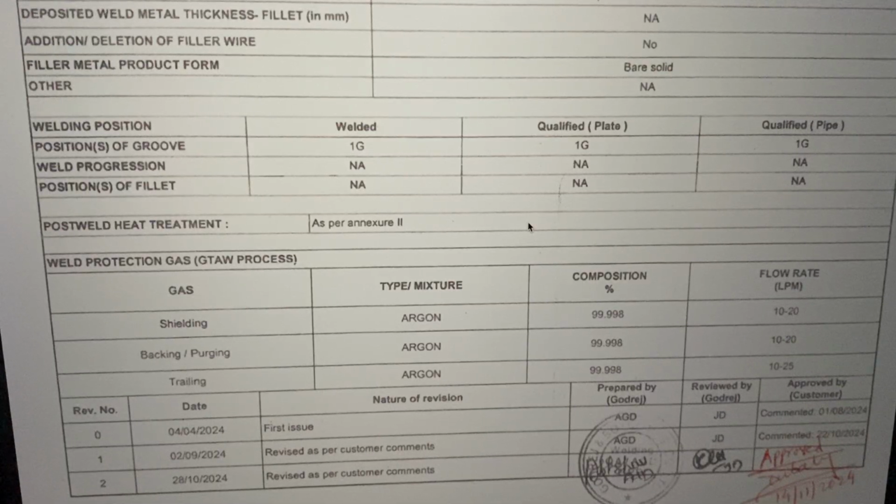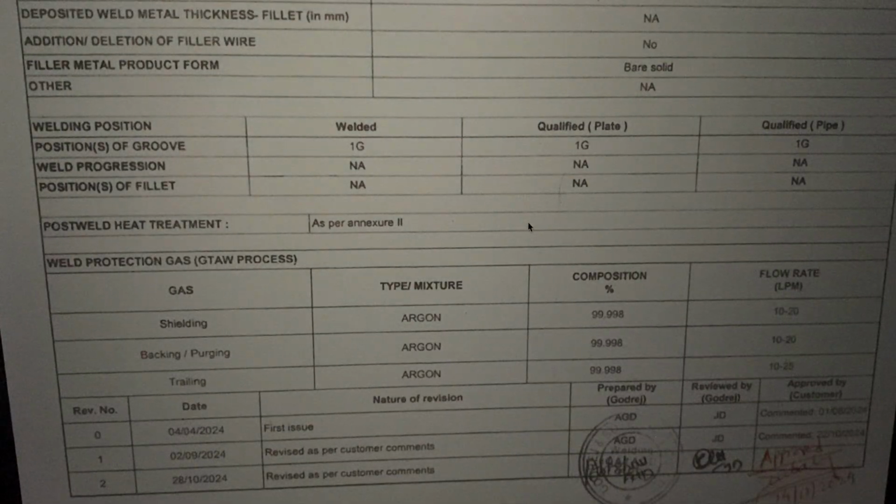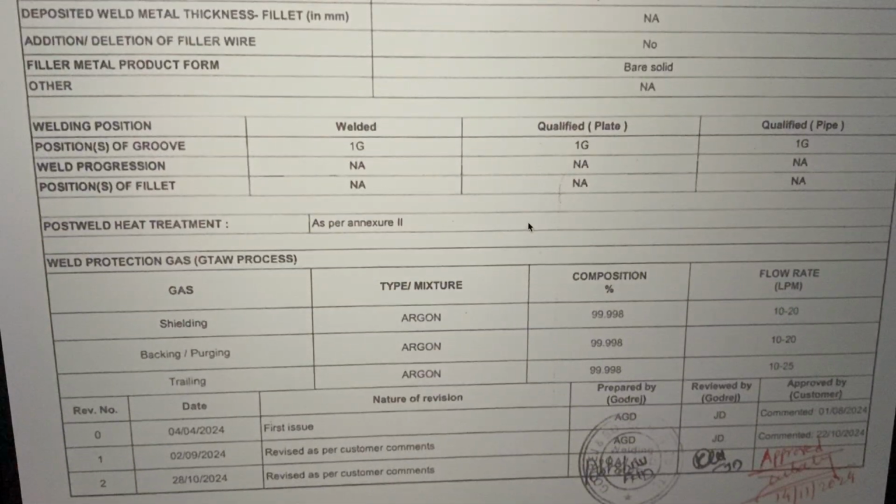We cannot assume that I have a lot of machining allowance, and so let it distort or let it have some other shape. I will correct it by the machining allowance I have kept. But we forget that when we do that, already the joint is stressed, the equipment is stressed, and we are going to further stress it by machining.